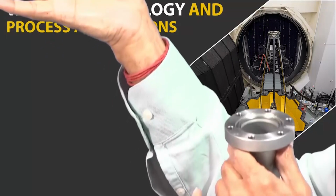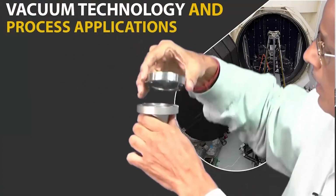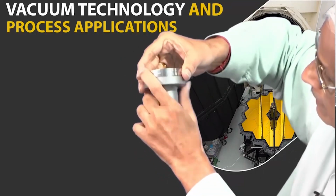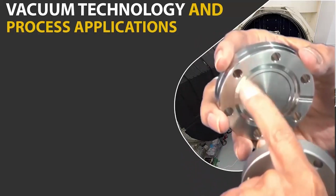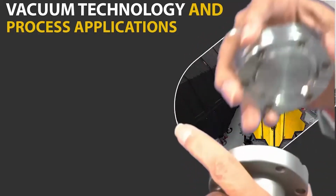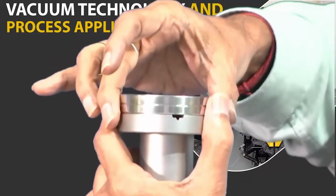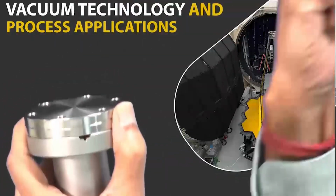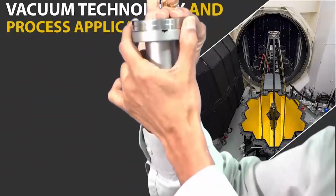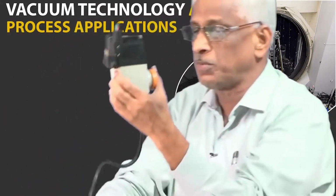You see how shining it is, because these are all ultra high vacuum, and you have to put that, within that a copper gasket is there. So, this cone will apply huge pressure on that copper gasket, so that yield stress will cross and it will form a seal. There is no polymer here. So, you try to tighten it with a good torque, so that it forms an all metal seal for ultra high vacuum.